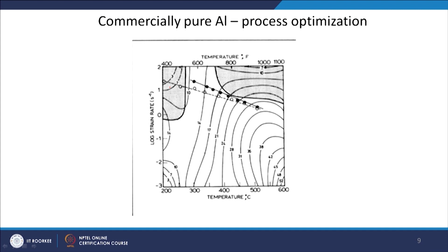Again, you want to have good productivity and you do not want to have large heating. Of course, the first pass is here, and this is my last pass. So, 2, 3, 4, 5, 6, 7, 8. This is the last rolling pass. From high temperature my material is continuously getting cooler and cooler.